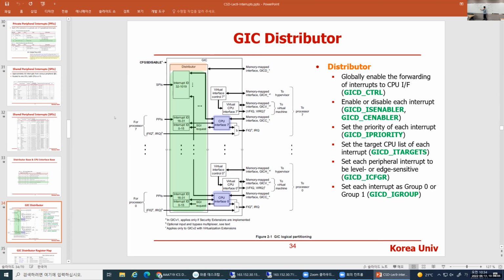Okay. And some interrupts come from your custom logic. That is inside the PS, the processing system in the Zynq device. And inside the PL, probably you want to implement your custom IO device. Let's say that is a GPIO. The GPIO is integrated inside the PL and generates an interrupt.